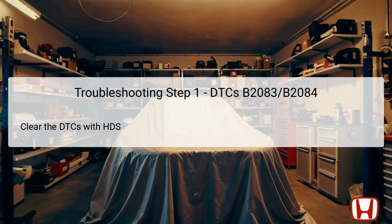Before proceeding, ensure the HDS is connected properly and that all previous fault codes have been documented for further analysis. After clearing the codes, it's crucial to continue to the subsequent troubleshooting steps to capture any fresh data, which will assist in uncovering underlying problems affecting the right power sliding door mechanism.